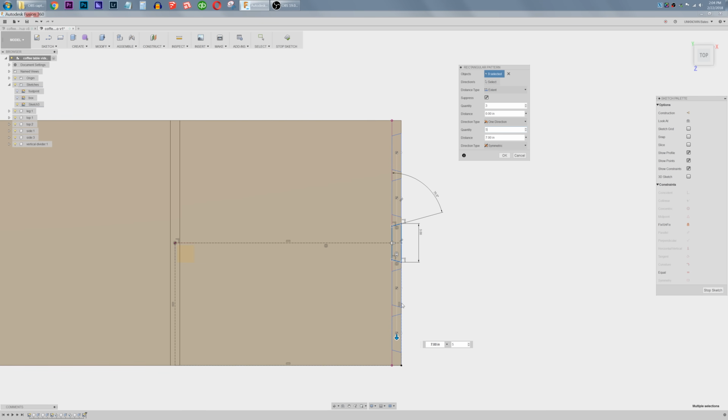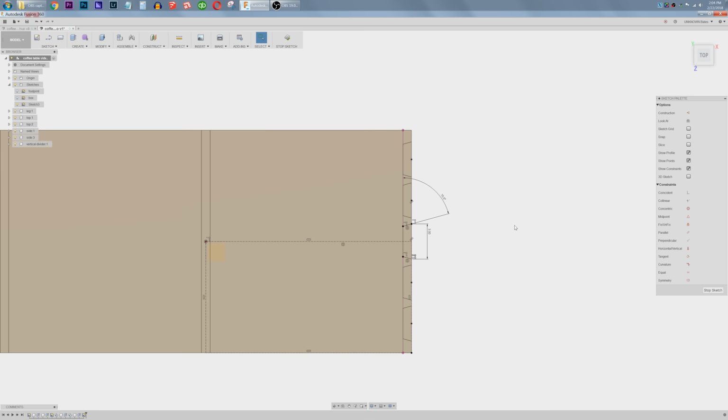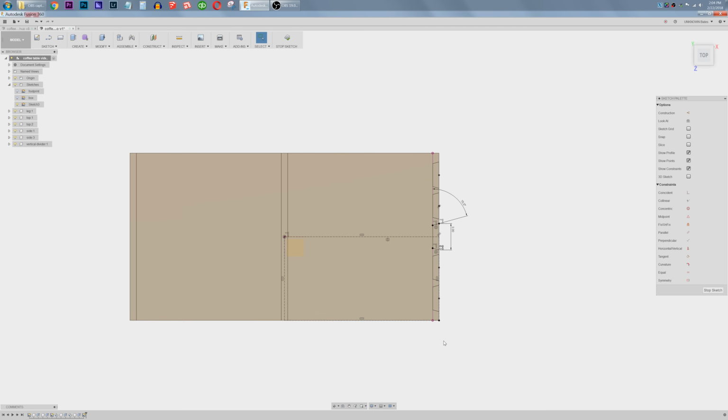And it keeps this dovetail pattern kind of enclosed to the middle of the project. It visually breaks up the outsides. I like that. So I'm good with that spacing. I'm going to press OK. Now, I also want to mirror all of this to the other side. No sense in drawing it again. So let's go to Mirror and select all of this, mirror line right there. Press OK. And all of my dovetails are taken care of now, both sides.